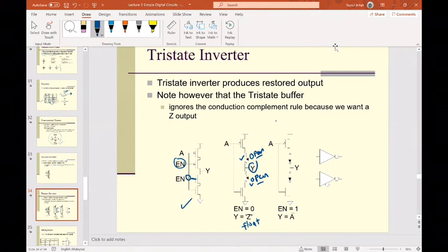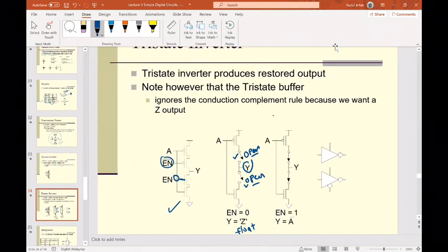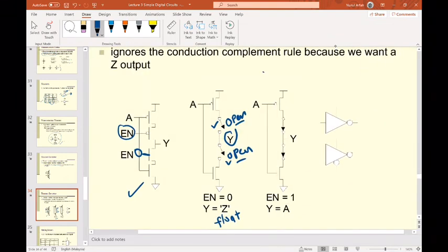All right. And then we have another condition when enable is equal to 1 here. If this is 1, then NMOS should be turned on. So that's why you have a turn on side. And then when we negate the enable, you have a 0. If you supply the gate of PMOS with 0, then this one will be turned on. That's why you have a switch on for both sides.